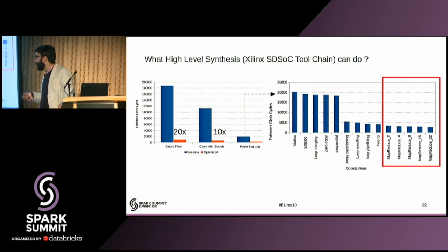But when you put these accelerators back into the Spark runtime system and measure the end-to-end execution time, the speedup is not more than 1.5 to 1.6x. But if you want this 20x acceleration, you can do that just by learning high-level synthesis and the Xilinx SDSoC toolchain. Man, it's a matter of 3 months, and you could also start showing the same numbers.